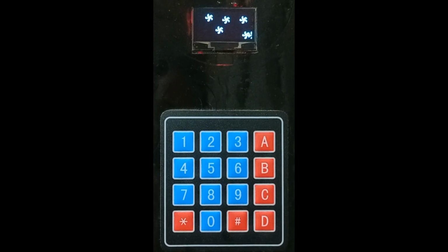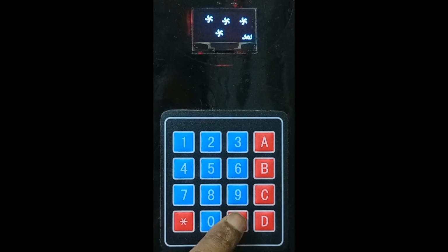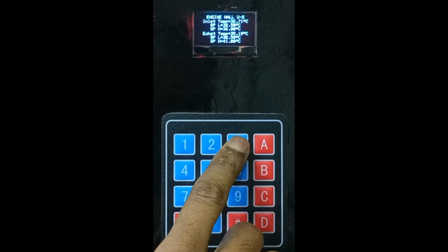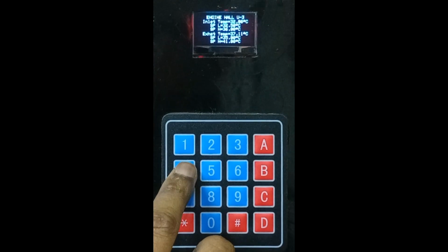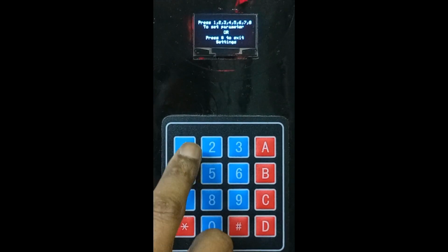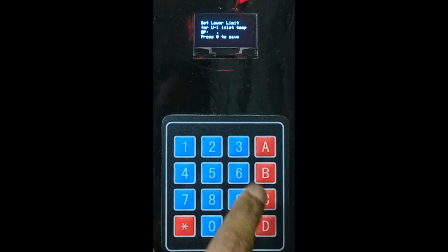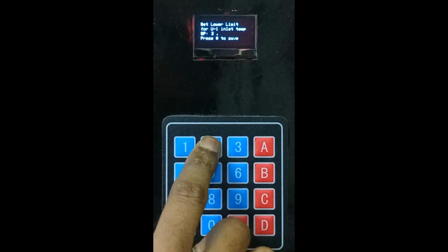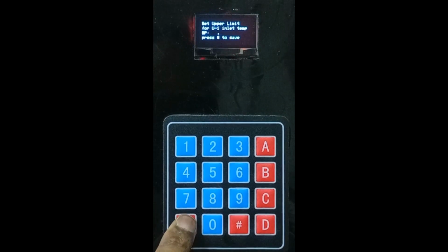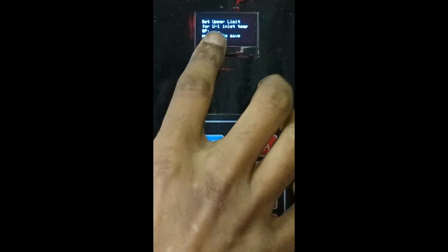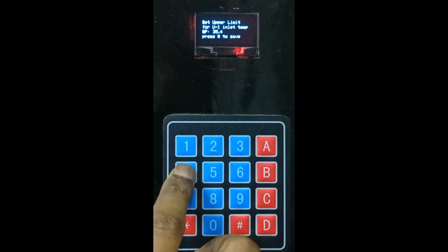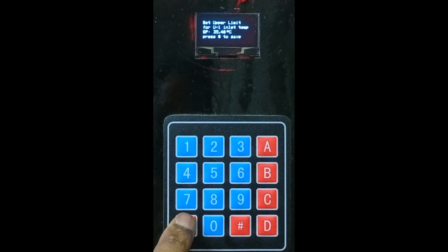Now let's see the parameter setting physically. Here I alter the pace to see the changes. Now let's enter the setting menu. Here I press 1 to set the parameters of ventilation fan number 1. The lower limit of ventilation fan number 1 has been set. Now set the upper limit. Okay, the upper limit has been set.